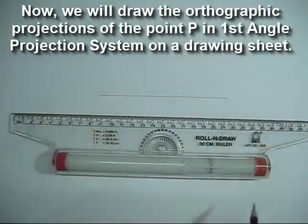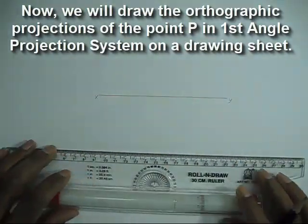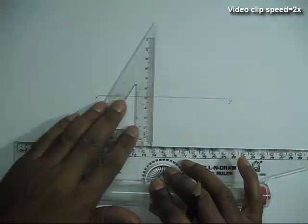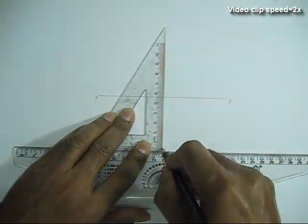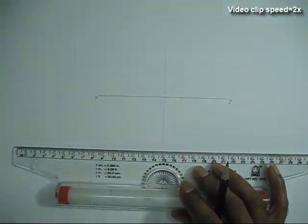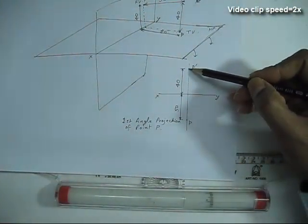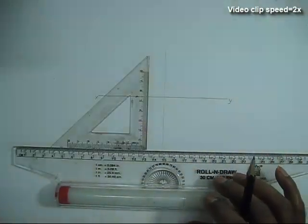Now we can see how we can draw it on a drawing sheet. So again start with the reference line XY. Draw a line which is perpendicular to the reference line. The front view and the top view both will fall on this perpendicular line. So the front view is above the reference line. The top view is below the reference line.